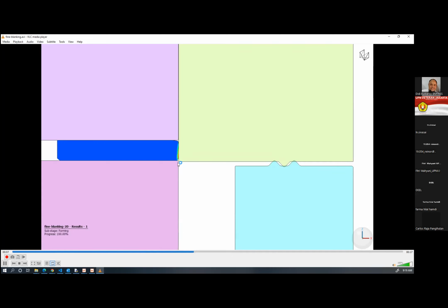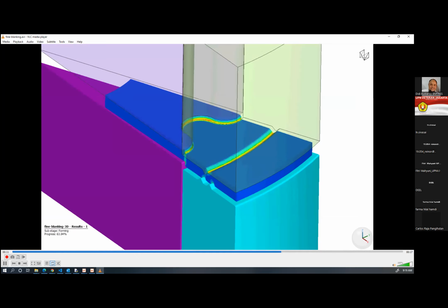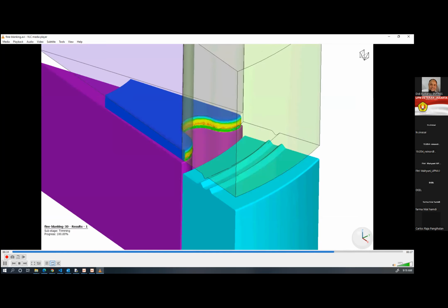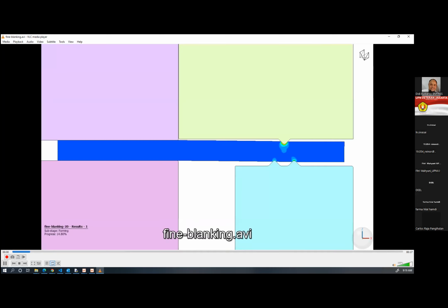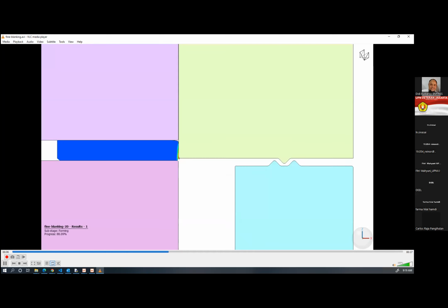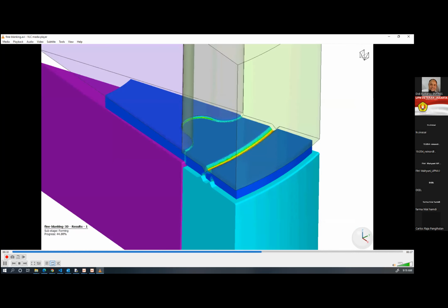So in SIMUFACT, we can specify this type of conditions really easily. The whole ultimate aim is that it is being deformed, so that's why it will be trimmed at the last stages. That's why SIMUFACT first deforms it and then trims it. Or if you don't want a deformation based trim, if you're looking for only a Boolean operation trim, that also can be done in SIMUFACT forming.